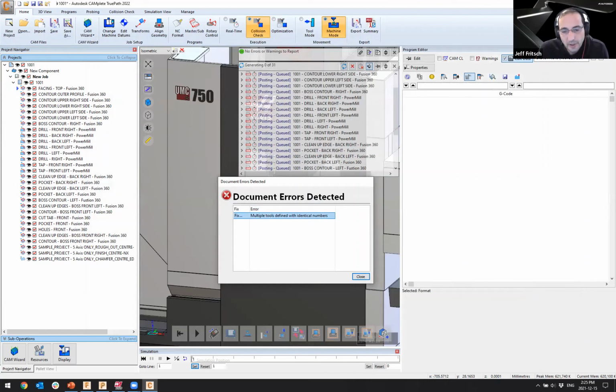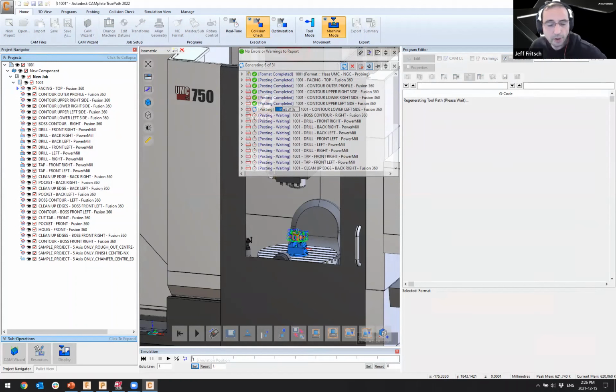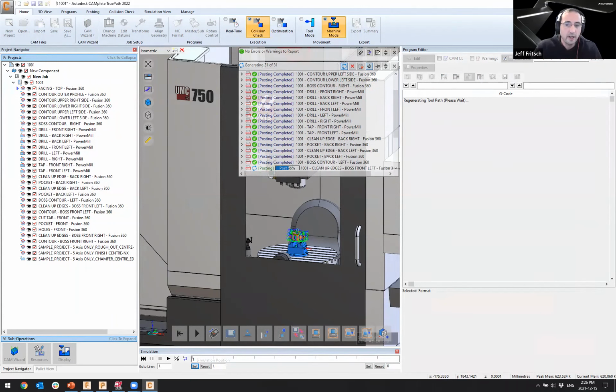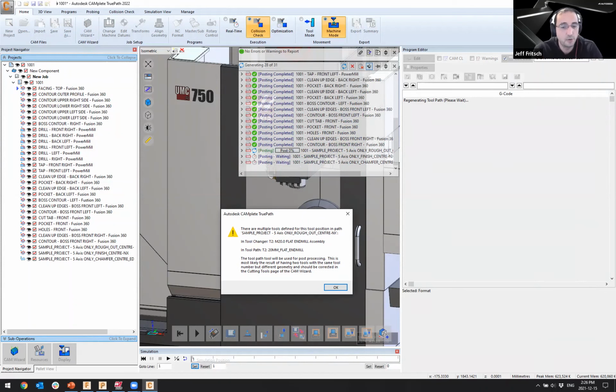So in that particular case, we'll see that now we'll have some conflicting information about tooling. That is one of those issues that comes up very, very often working with multiple CAM systems. Of course, there has to be a match on the tooling side. So in that particular instance, as we're producing the code, we'll flag some of those issues and say, okay, this is an instance where we have the same tool number used twice, but the tool geometries associated with each tool are actually drastically different, or different enough that that would have an impact on the results of the part.